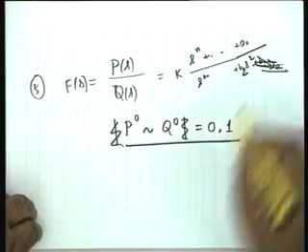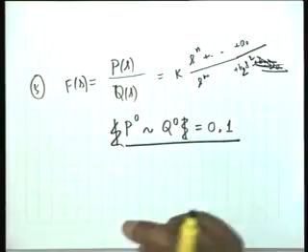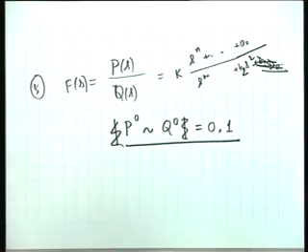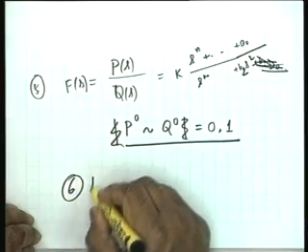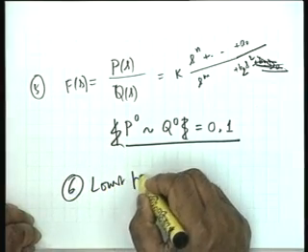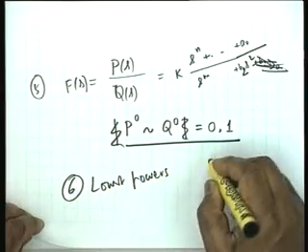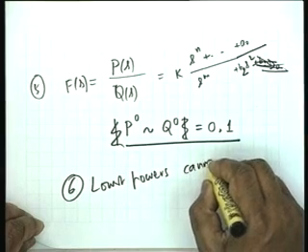Can we have in the denominator b0 and b1 both absent? That is right. What does this mean? That the lowest powers in numerator and denominator cannot differ by more than 1. Okay. So this is the sixth property. Lowest powers in numerator and denominator cannot differ by more than unity.